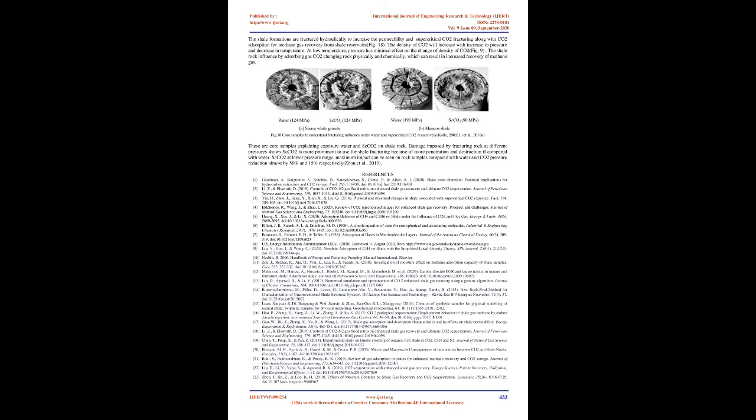Fig 14 A shows the interaction of shale with different saturation pressures of CO2 and the resulting UCS and elastic modulus changes. One can interpret through the graphs that UCS strength and Young's modulus both decrease with increasing saturation pressure of CO2, resulting in reduction in mechanical stability of shale. Through this, one can also interpret microstructure alteration under the influence of CO2, resulting in the swelling of shale, adsorption/desorption, and micro cracks.